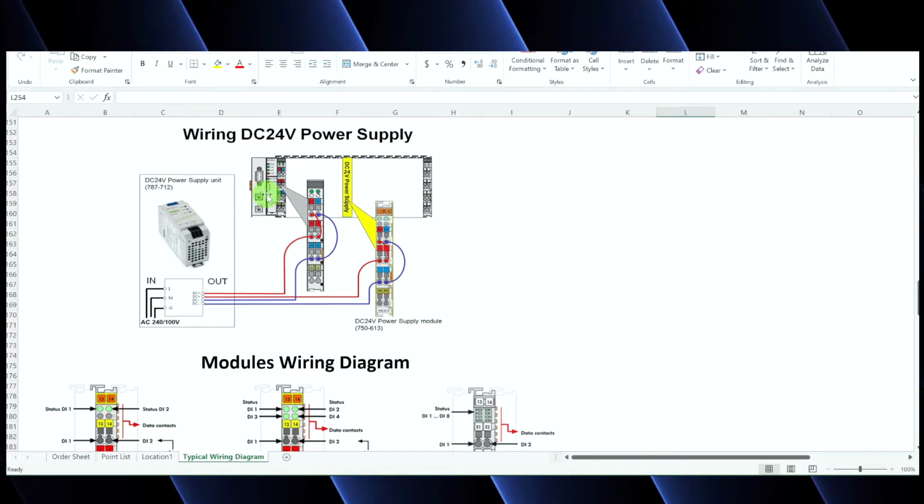You also want to make sure that you wire this properly. So you're going to run your DC positive to this contact exactly like it shows on this diagram. You're going to run your positive, your minus, and then you're going to run the other side of that up and the other side of that up. And that way we can power all of our strips.